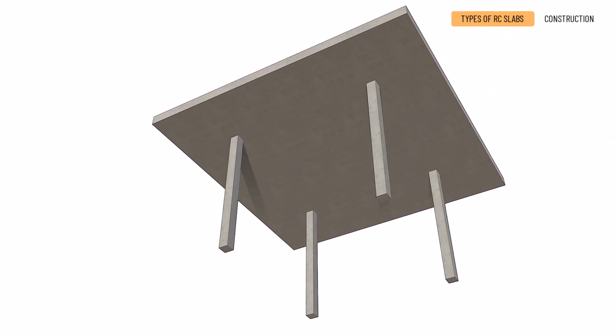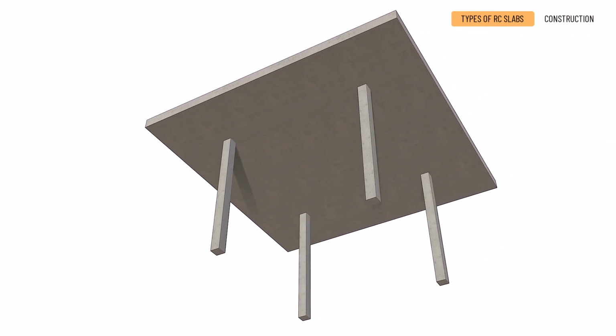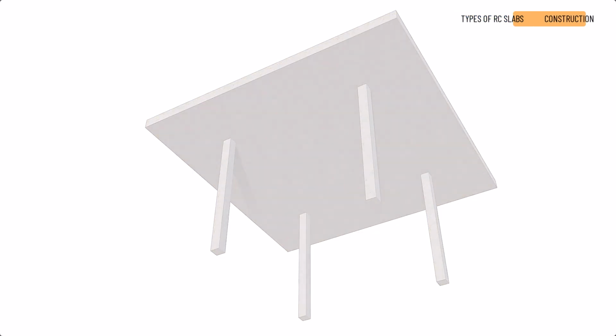creating a completely flat plate on the entire top and bottom sides of the slab. This further increases the required slab thickness, as the anti-punching shear reinforcement must be completely hidden in the slab. With respect to the challenges of reinforcement installation, this is the most practical monolithic reinforced concrete slab from an aesthetic, serviceability, and formwork point of view.